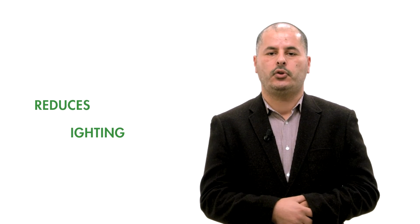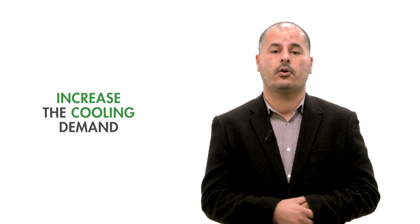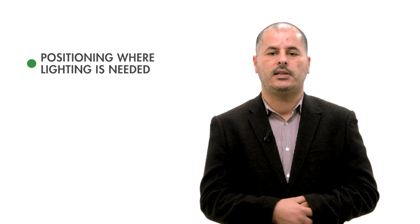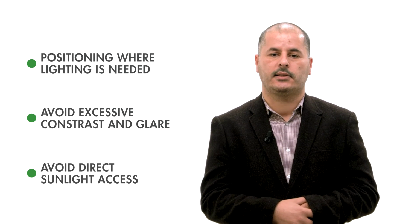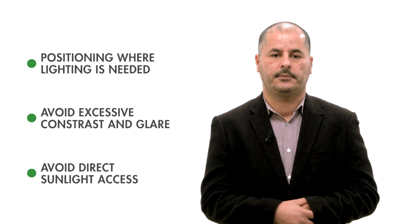Daylight access reduces the need for artificial lighting. However, these openings allow solar heat gain, which can increase the cooling demand. Accordingly, the following strategies need to be considered. Positioning of windows where lighting is needed. Avoid excessive contrast and glare. Avoid direct sunlight access. Small windows in thick walls could be efficient.